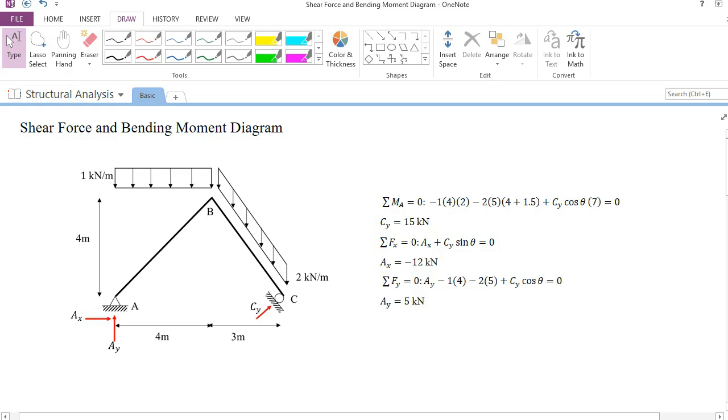The first thing you need to realize is that for the first distributed force, the per unit length in this kind of schematic drawing is with respect to horizontal distance. Well, for the second one, the per unit length is with respect to the slope, along the slope.